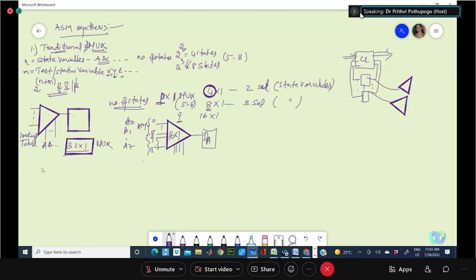But imagine the complexity of the design if that ASM is having 32 states. It's very huge, of unusual size. Actually, we don't try to take that many states because we are taking this in a top-down approach. We try to cut that down to some manageable 5 to 10 states only.